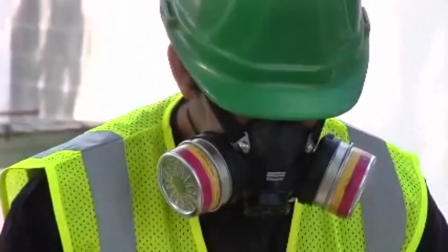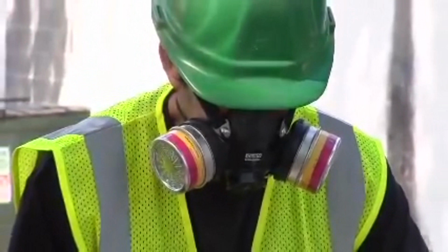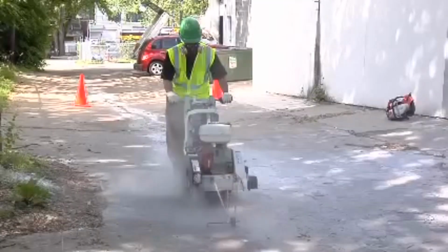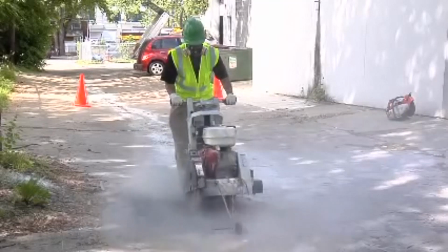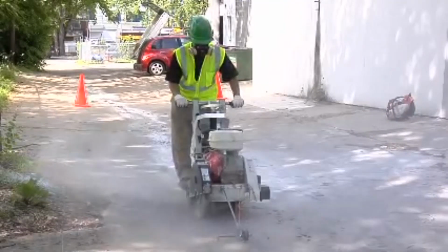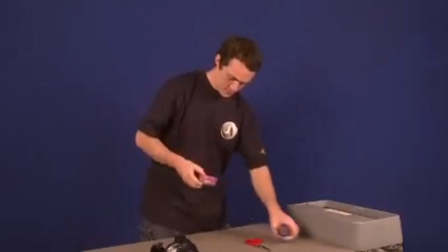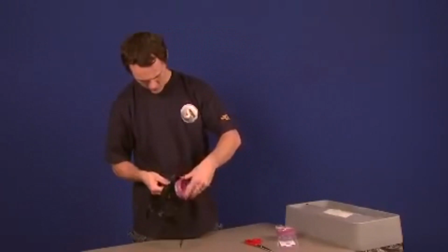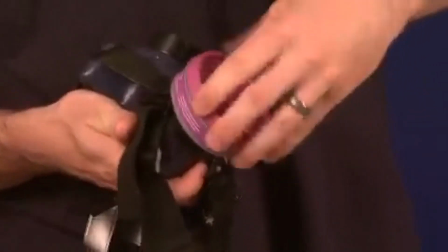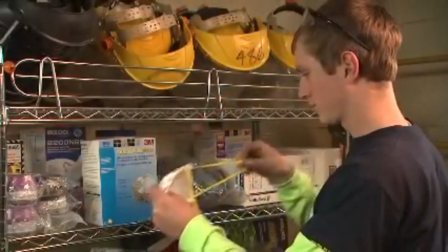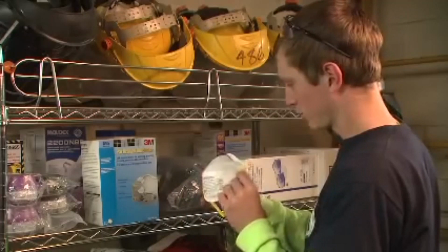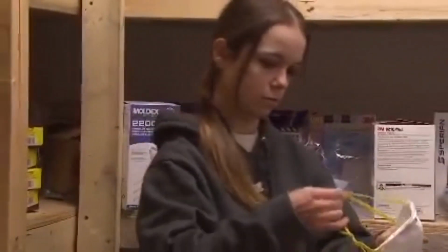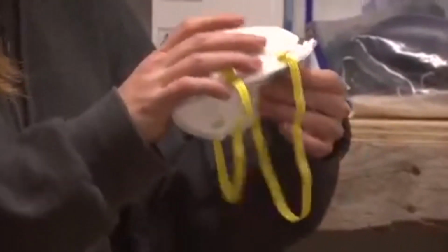Air purifying respirators use a filter or cartridge to remove hazards from the air you breathe. A properly functioning air purifying respirator can provide effective protection for as long as the filters or cartridges work correctly. For respirators that use filters to clean the air, the filters must be replaced whenever they are damaged, soiled, or cause noticeably increased breathing resistance. Before each use, the outside of the filter material must be inspected. If the filter material is physically damaged or soiled, the filter must be replaced, or in the case of a filtering facepiece respirator, the respirator must be discarded.